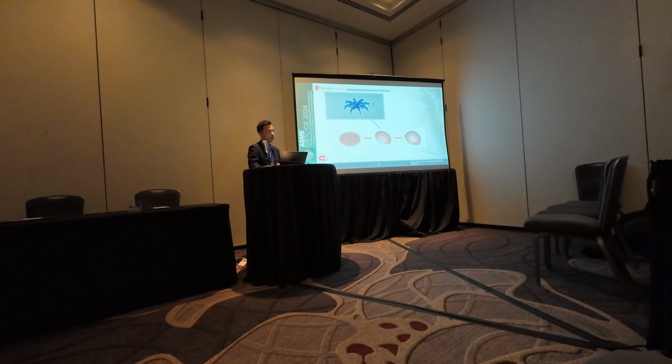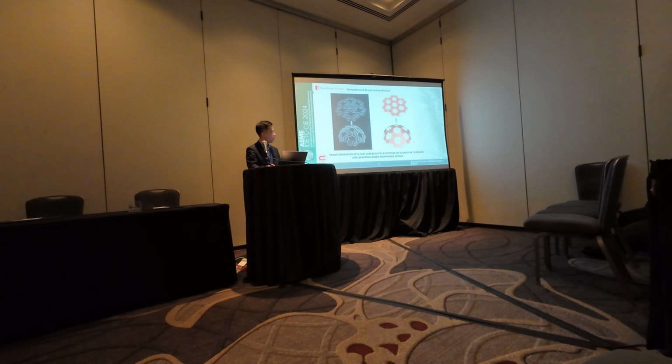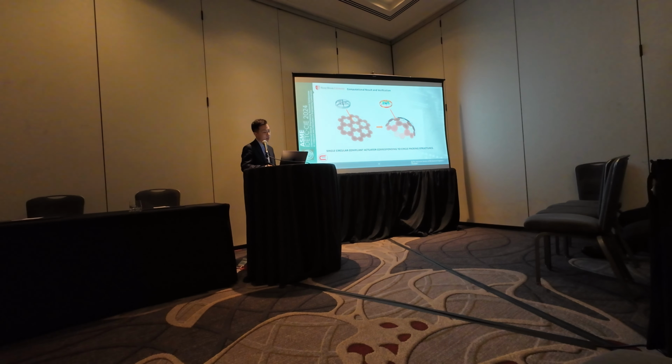Each of the circular mechanisms represents each circle in the circle packing. If we cover it, surrounded by a cylindrical wall, we'll do the verification again. And here is the transformation of the flat surface to a complex 3D geometry through the circle packing based workflow design. You can see each of the circles can be represented by each circular mechanism, a single circular compliant actuator corresponding to the circle packing structure.